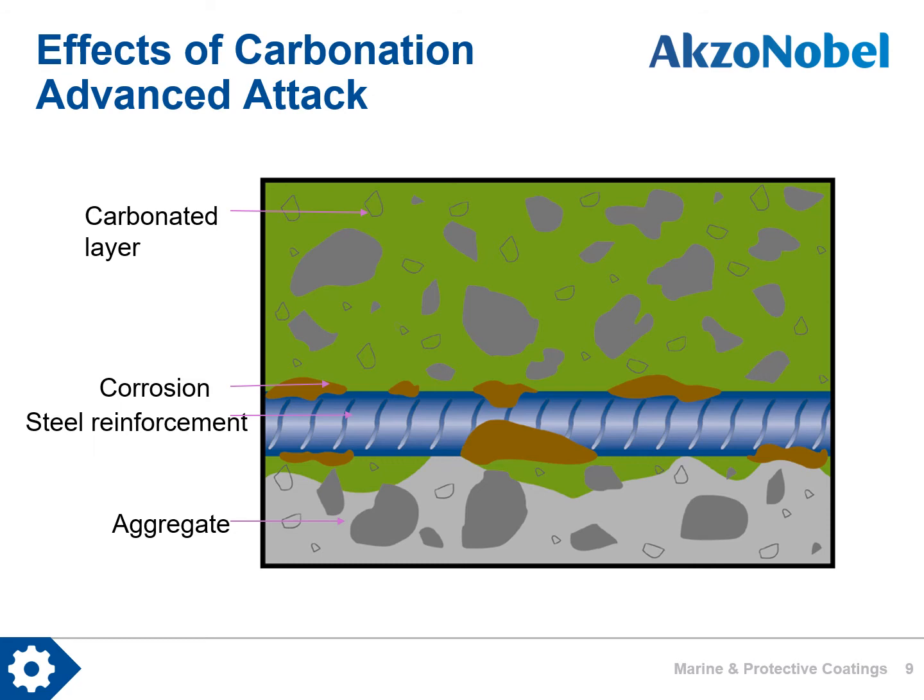The rate of carbonation is dependent on a number of environmental factors. For example, because it is 10,000 times more difficult for carbon dioxide to pass through a water-filled pore, carbonation is not a threat in totally immersed conditions. However, a critical factor is the quality of the concrete cover, as poorly compacted or weak concrete will offer little defense against carbon dioxide ingress.